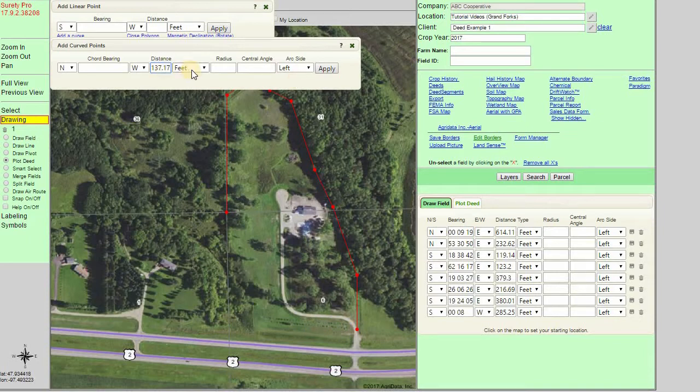And a radius of 3270.46. So we can have a radius here, 3270.46. Central angle, 2 degrees, 24 minutes, 11 seconds. And the chord bears north, 85 degrees, 55 minutes, and 39 seconds west. So we have all this information filled in here. You actually don't need it all. If you have 3 of the 4, it will also be able to calculate it manually.